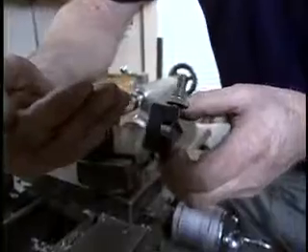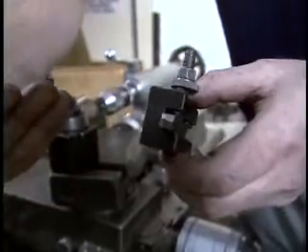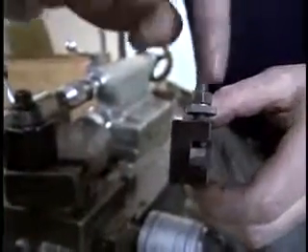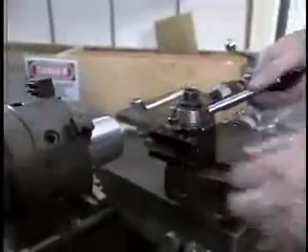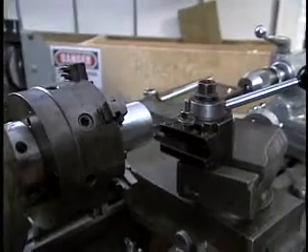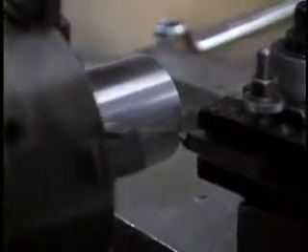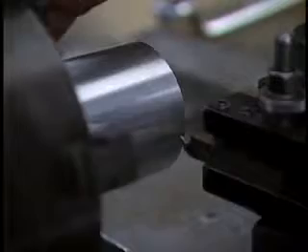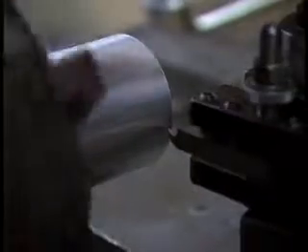You can see that the top of the tool is tilted to an angle like this, so that as you're cutting in this direction, the chips come down onto the tool and slide off the tool nicely. Start by bringing the tool close to the part, then turning the chuck. Doing this to make sure there are no interferences, either between the tool and the part, or between parts of the chuck and the rest of the machine.